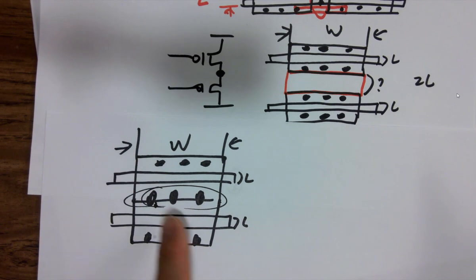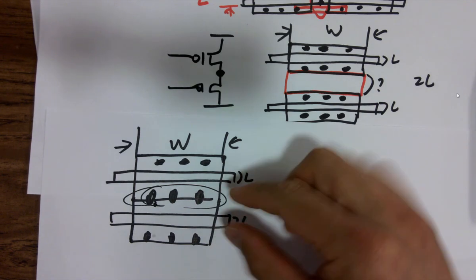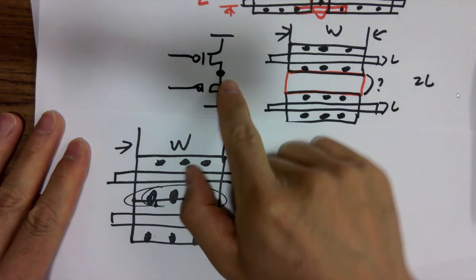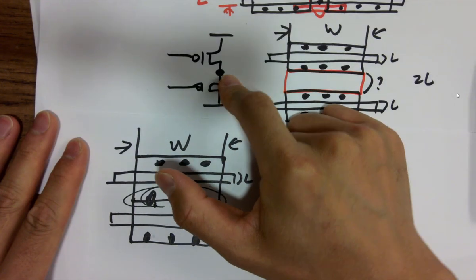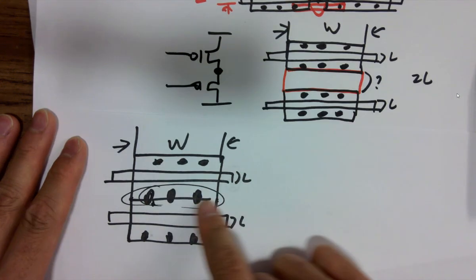Do we still need these vias and metal one in the middle? So basically, it looks like we only need two channel lengths, right? Is there anything else we can do? I guess technically you could do metal on the beams to have a better connection. If we don't really use metal vias or metal wires in the middle, we don't really need this at all.